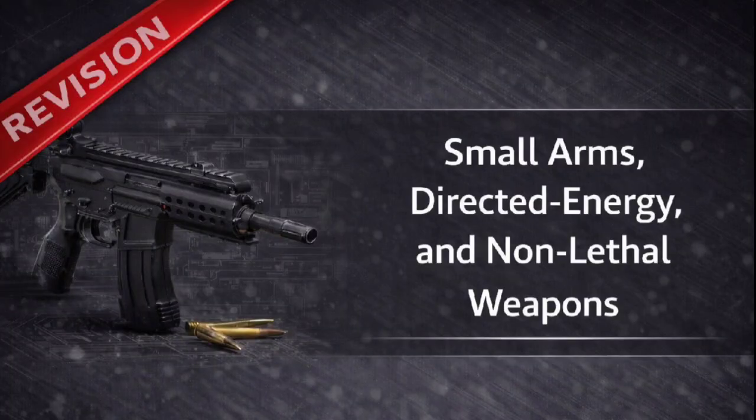Okay, let's define these 10 essential operations. We'll go in order, starting just after a shot has been fired. All right. Number one is unlocking. The breech mechanism is released from its secure, locked position against the barrel. Step 1, unlock. Step 2, retracting. The breech block starts moving backward, and it begins to draw the spent case out with it. Okay. 3 is extracting. The empty case is pulled completely free from the chamber. 4, compressing. The return spring, which powers the forward movement, is compressed, storing energy. And then you have to get rid of the old case. That's step 5, ejecting. The spent, empty case is thrown clear of the gun's mechanism.